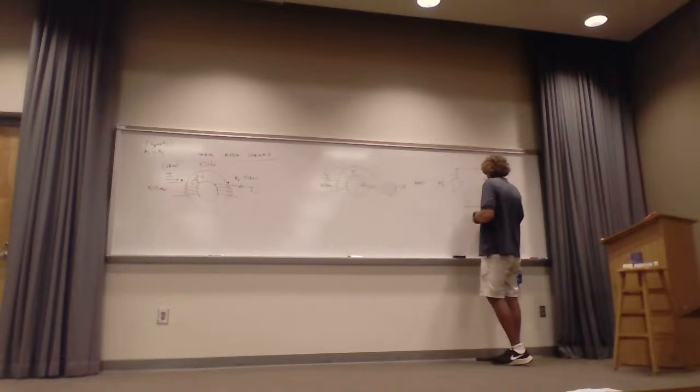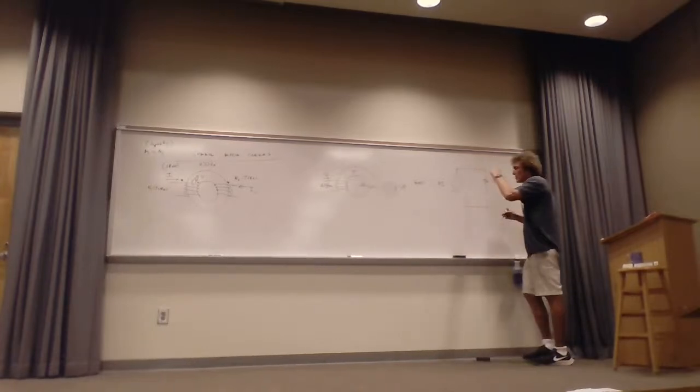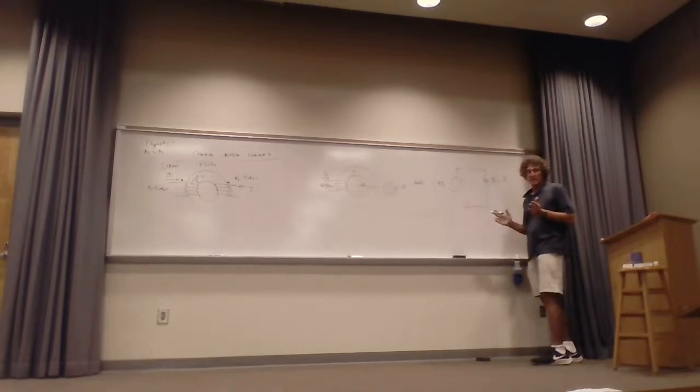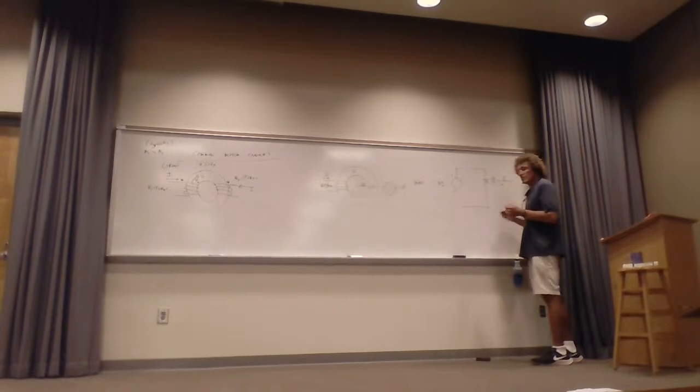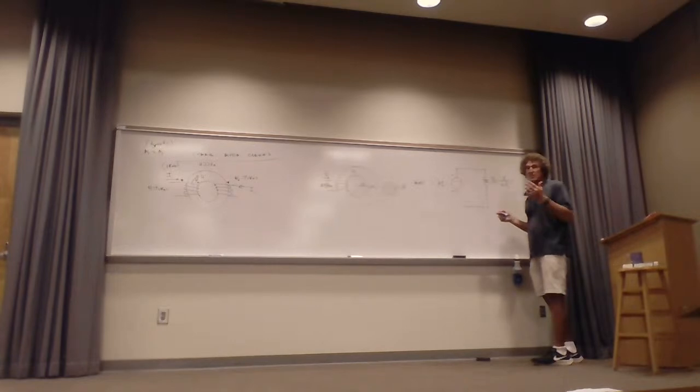The reluctance is always going to be proportional to the total length for a single element with a constant cross-section, inversely proportional to mu, and inversely proportional to the cross-sectional area. It's identical to the resistance formula for constant cross-sections, L over A, except instead of sigma, you have mu. You all with me on this? Now that's the reluctance.